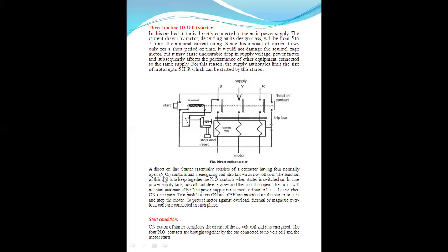A direct online starter consists of a contactor having four normally open, that is NO, contacts, and an energizing coil, also known as the no volt coil.